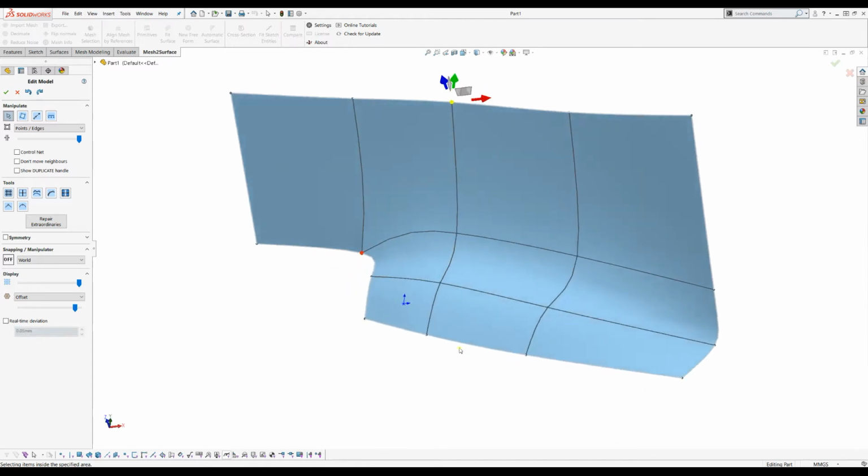So this video will just speak about our first tools here, which are called increase resolution and split edge. The increase resolution is a really simple command. It takes all the visible quads that you see on the screen, and takes every quad and splits it into four smaller quads. This is useful, you will see later, when you build a really rough shape of the object over the mesh, and then you want to get closer to the mesh and get better accuracy. So the command is really simple.